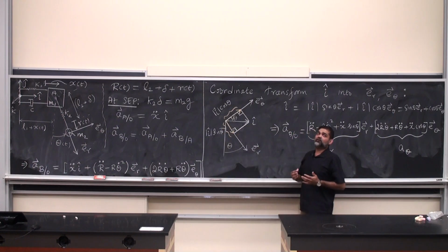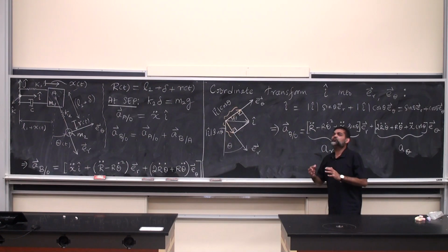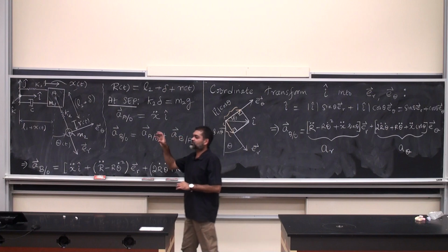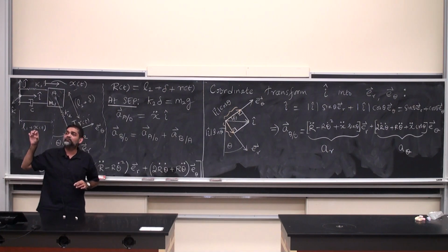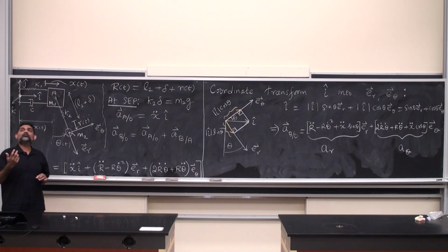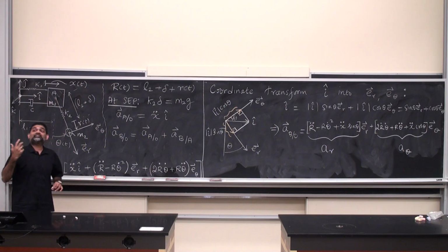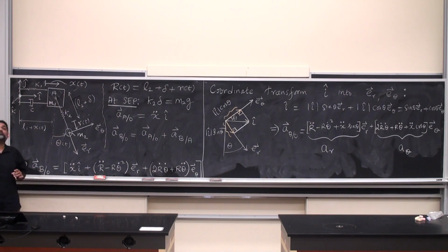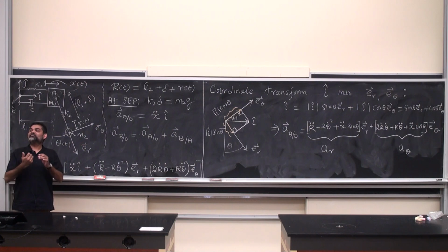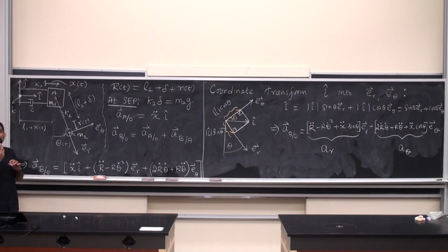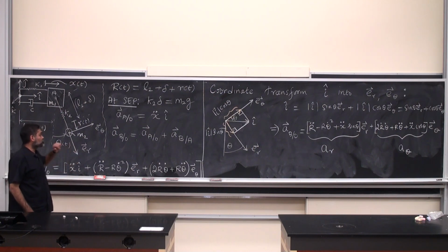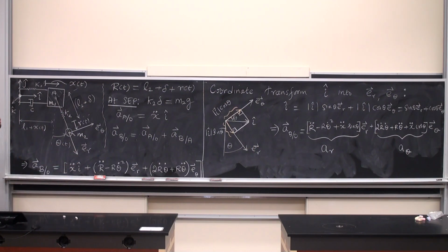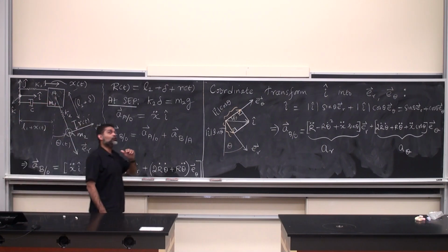Then we decided on the number of degrees of freedom. Common sense tells us that the mass can travel only horizontally, so it has 1 degree of freedom, mass m1. Then the springy pendulum, because it's not a string but a spring, has 2 degrees of freedom, restricted to motion along the xy plane, the plane of the board. Those 3 degrees of freedom are marked in the figure: x of t, theta of t, r of t. They are all functions of time.